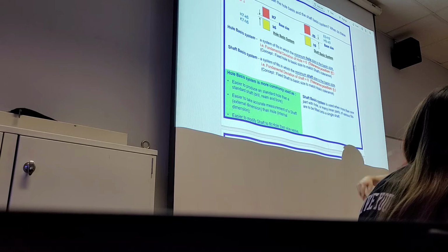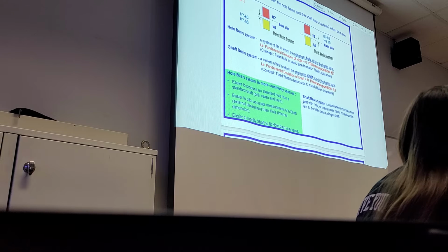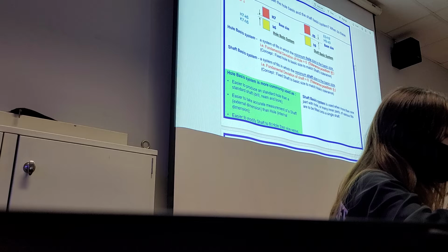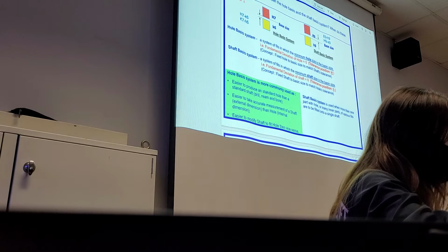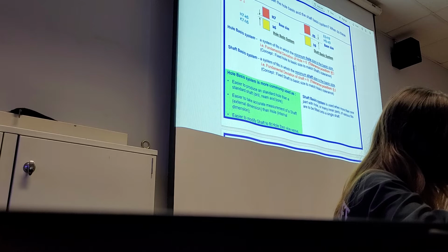Sometimes we use a shaft-based system in very special cases, like one shaft fitting with many pieces. Otherwise, we always use the hole-based system.